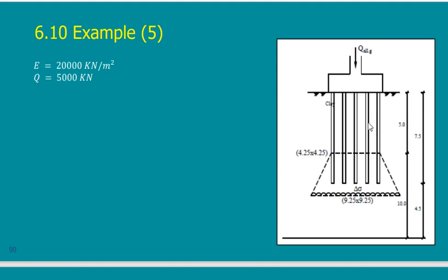This you can calculate based on your previous calculation, what is the load that will be carried by a single pile. Multiply it by the number of piles, then this is the maximum that the group can carry. And calculate another thing. What is this other thing? That instead of the piles being attached to the soil, the pile and the soil were detached from the full mass. So in this case, I will have to calculate the weight of a block.